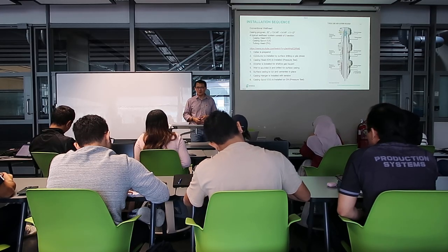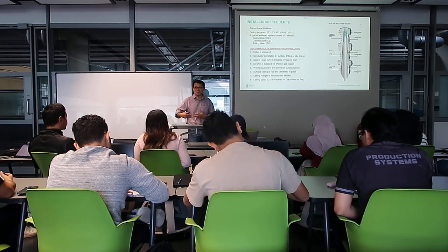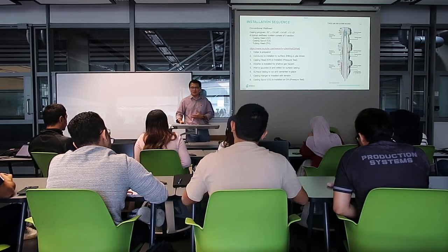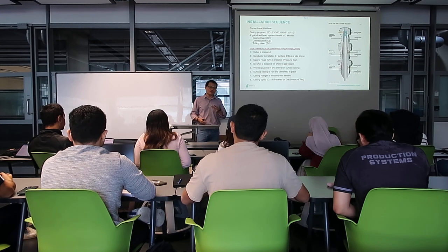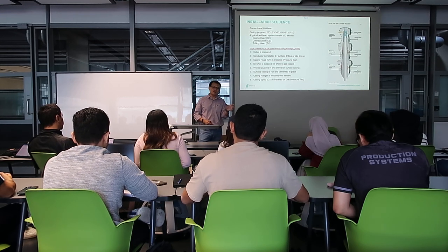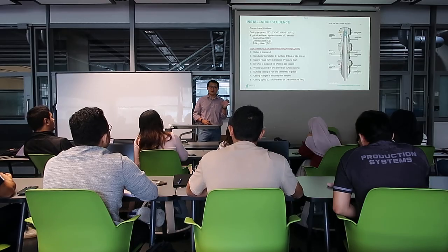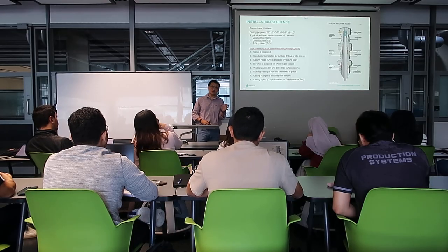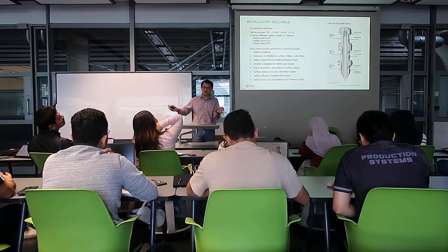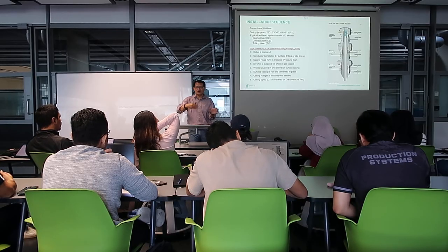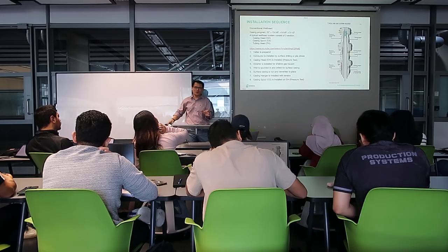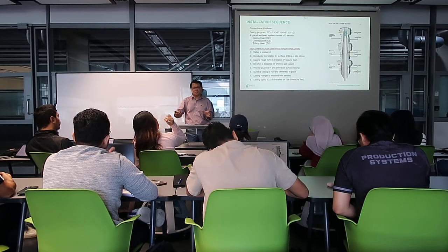Any clue? Why we must test it as soon as possible? Yeah, so operation wise, we want the seals to be good, holding before you move on. But nowadays there are some wellhead designs where you can only do the test after you put on the next wellhead, and then only you test.